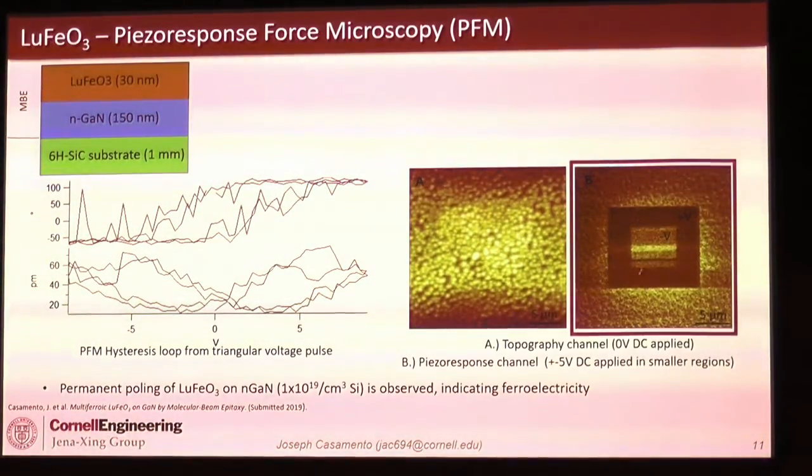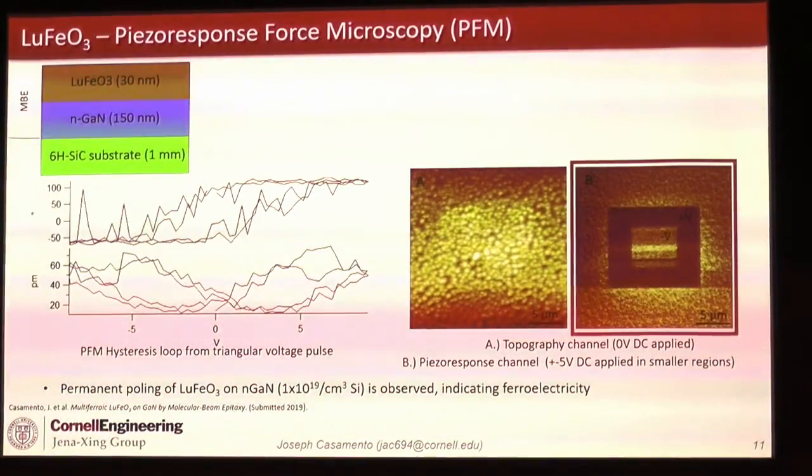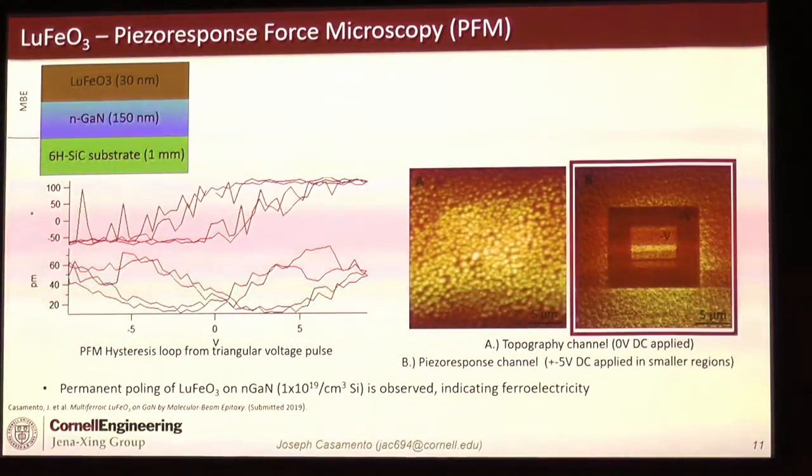And from this, we're able to pole the surface in opposite polarities and extract an approximate coercive field. And this poling pattern is seen even if you pole it, reduce the bias, scan, leave it for an hour, do nothing, and come back. You can still see this box pattern. So we believe that this is not just purely charge injection on the surface.